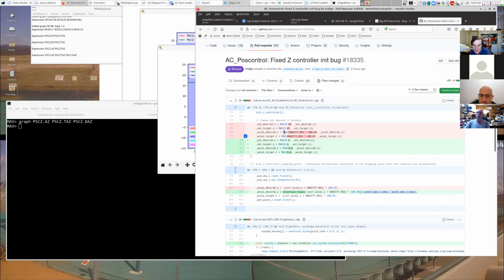And the second thing we were getting wrong is, when we were calling this special function, which is this no descent function, which is used when we're transitioning for a tail sitter in particular, where we want to go from forward flight upwards and we want to initially not descend, the max here was wrong. It should have been max of 0 and the desired, not max of 1G, because this was providing a minimum of a 1G vertical climb when we transition in a tail sitter.